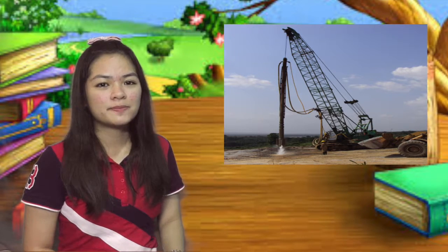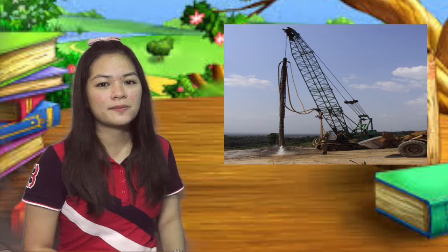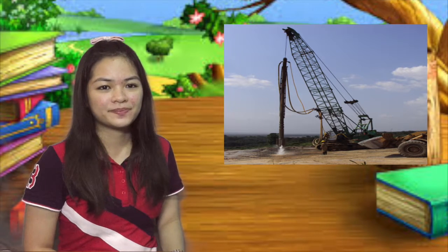However, vibrocompaction is a broader term that encompasses 2 different techniques. The first is vibroflotation, which uses a vibrofloat that vibrates horizontally. The second utilizes a vibrating probe which vibrates vertically. It should be noted that vibroflotation is used as a mechanism for implementing vibro replacement, a method which combines the technique of vibroflotation with gravel backfilling in order to create stone columns.